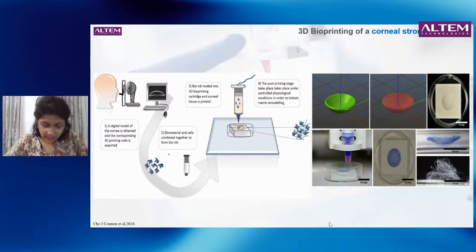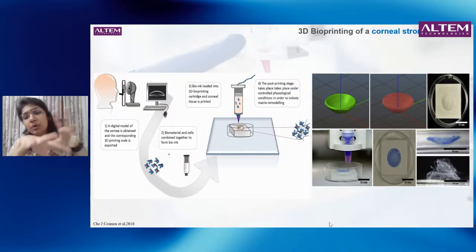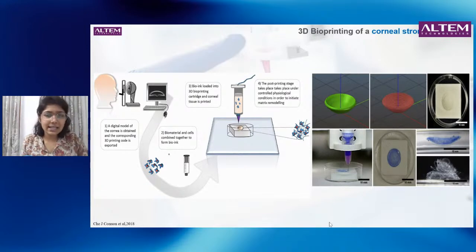Now, when it comes to printing this, you would have extrusion based printing as well as DLP based printing. When you have extrusion based printing, there is a possibility that you might require a support. Support being a material. For example, if I'm trying to create any sort of curvature with a material that could be slightly soft, I would require a support structure to print anything over it, to hold a structure which is concave or convex, right? That's where support is required.